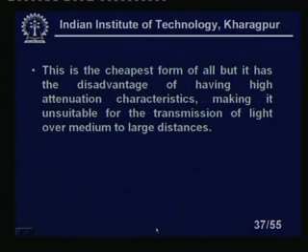This is the cheapest form of all, but it has a disadvantage of having high attenuation characteristics, making it unsuitable for transmission of light over a medium of larger distance. For a shorter distance, okay. Suppose I am using it as a sensor, pressure sensor, load sensor, that type of case is not a problem, but if it is used for transmission only, then it is not very suitable to use all plastic fiber optic cables.